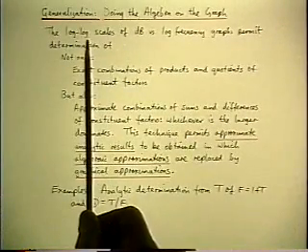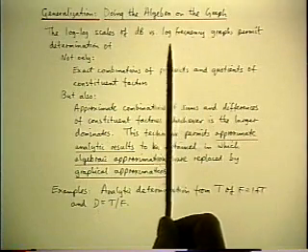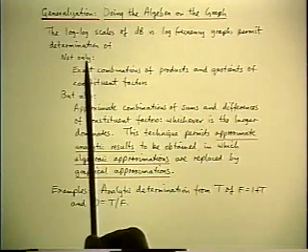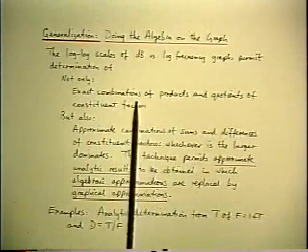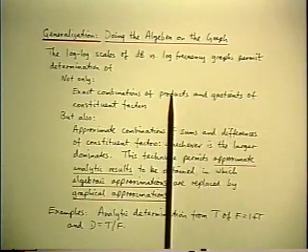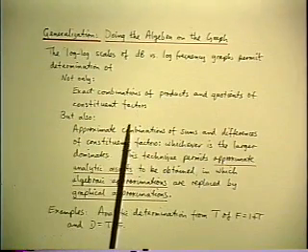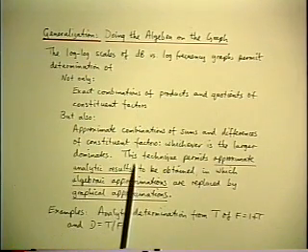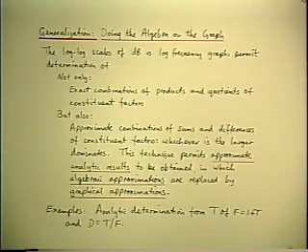So notice that using log-log scales for dB versus frequency permits the determination not only of exact products and quotients, because products, quotients convert directly into sums and differences of dB, but now you see how you can also do it to compute sums and differences. A technique that no one emphasizes in the textbooks.